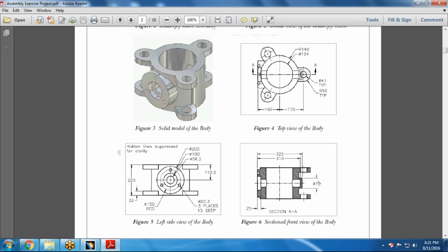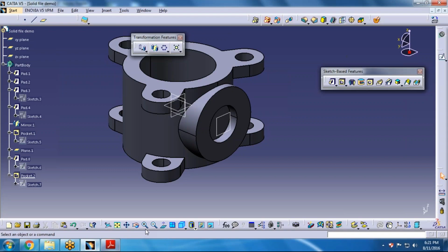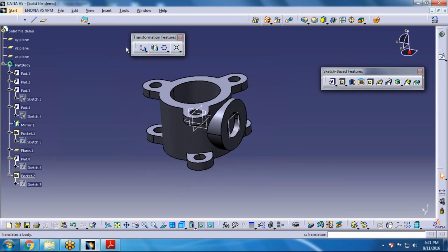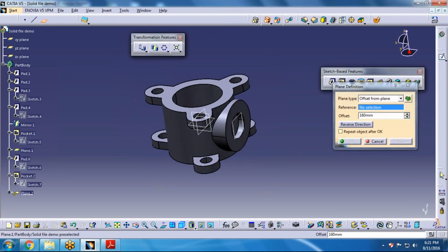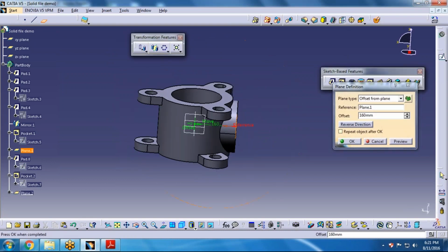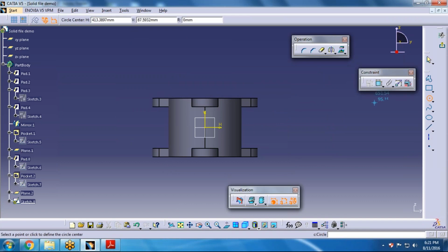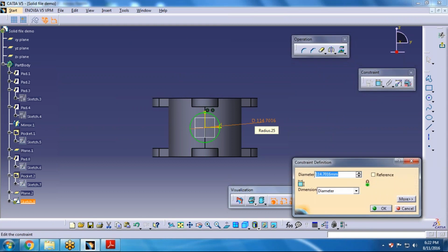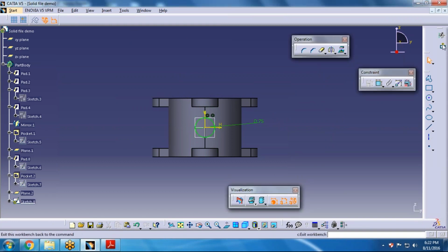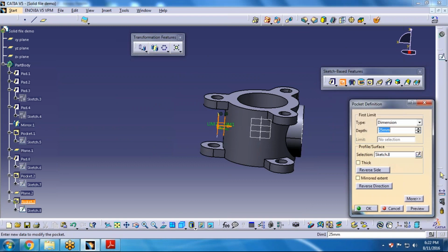So I'm just doing one thing, create a 175 millimeter diameter circle and make it extrude first. So I'm just going for one thing, make a new plane, create a new copy at the distance of 325. Now create one circle at this point and provide the size. The size will be 75 diameter. Exit from there, make a pocket up to next, and done.